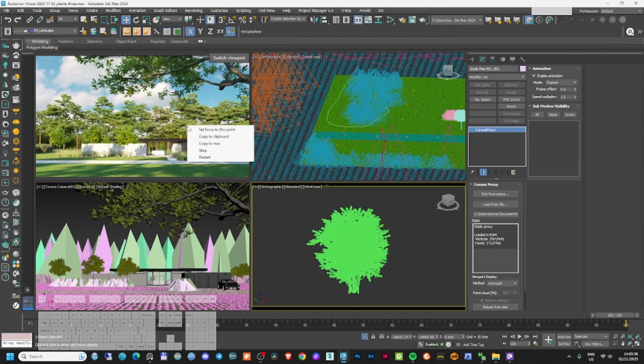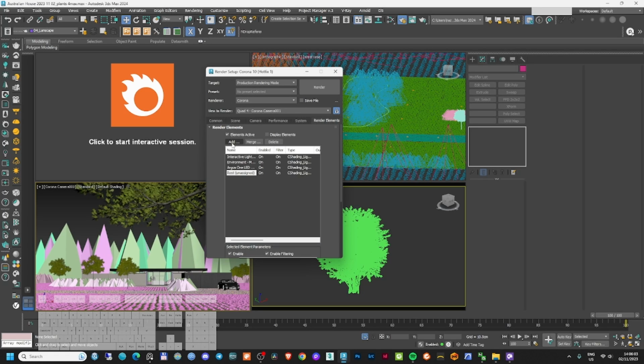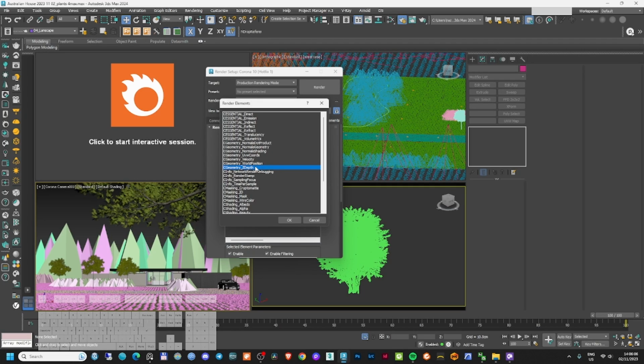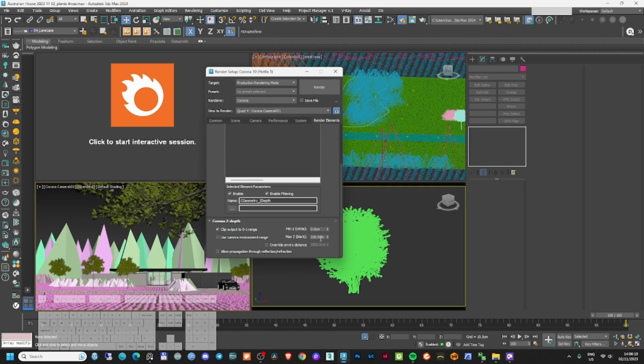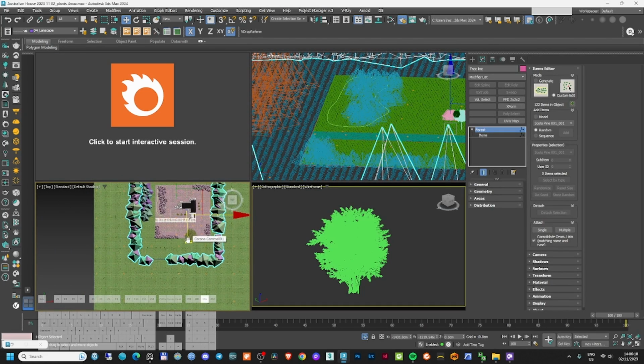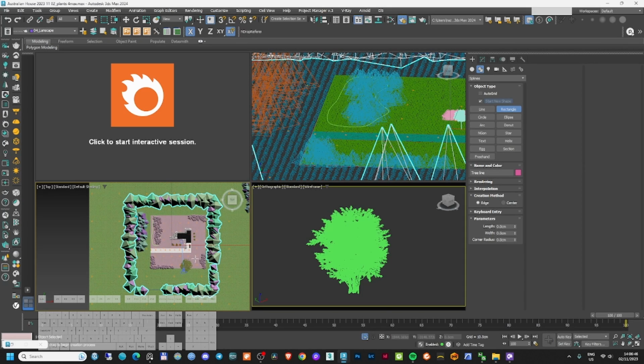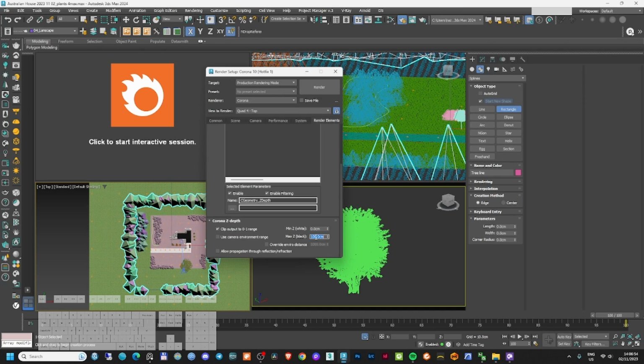Okay, let me just stop this for now and set up some light mix, noise limit to 0.5, 3500. I will add in here a Z-depth. This Z-depth can go from the camera to here in the back, so let me just calculate that. 90,000 centimeters means 90 meters. 1,000, 10,000.